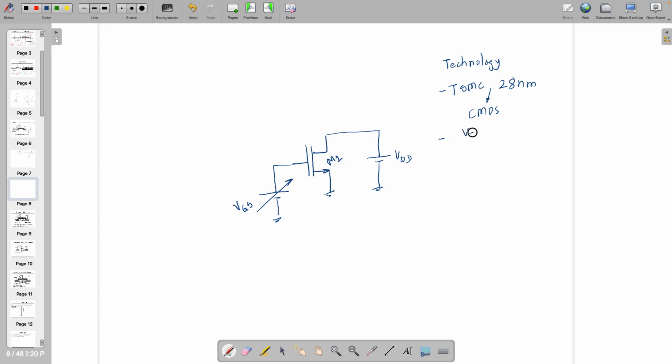Have you checked what the threshold voltage is? Sir, I 2.4. Okay. So before that, is it 2.4 or 0.6? What is VDD? What is VTH? 0.4 to 0.6. How do you know that 0.4 to 0.6 is a big number? Actually, I have asked this much. 476 millivolt, did you not see? These numbers have to be on your fingertip.